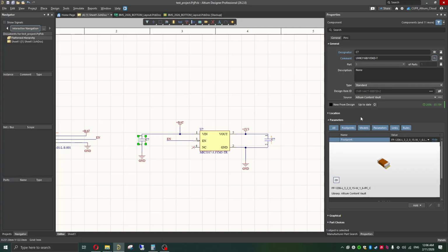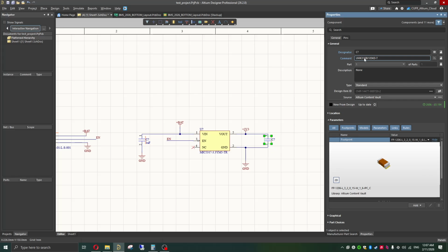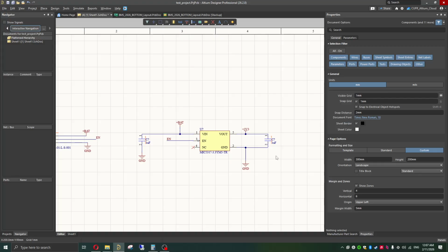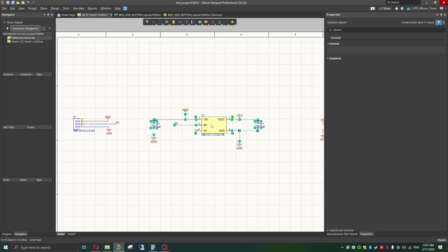These are all sized appropriately to be 1 microfarad. Actually, for additional clarity, instead of putting the part number on it, we can add a comment about the value of these capacitors. So, we can make this 1 microfarad, just for clarity's sake. Alright, pretty good circuit. Now, all that's left are the high-level aesthetics.